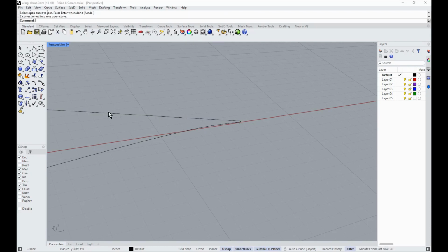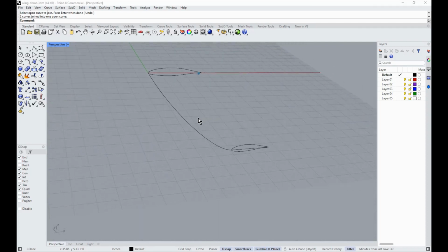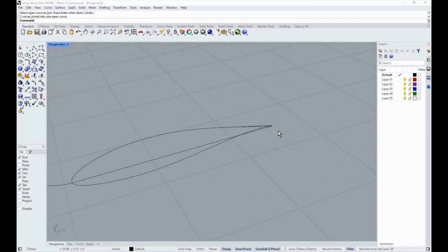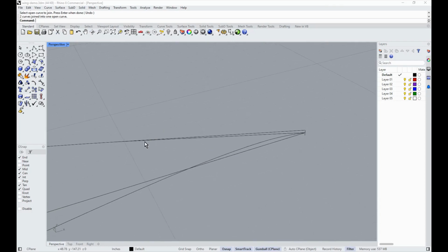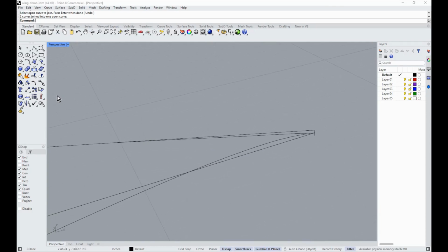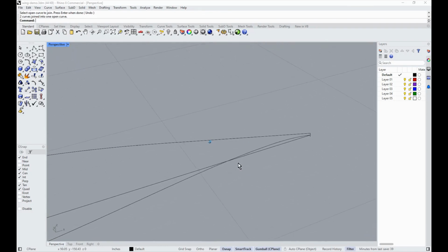So basically it's going straight here for the very trailing edge. If you're doing something like a composite wing or something like that, you can do this under curvature without too much trouble, but let's just assume we're going to make this out of aluminum and you don't want to make it difficult. So we've trimmed it and we're going to join it like so.